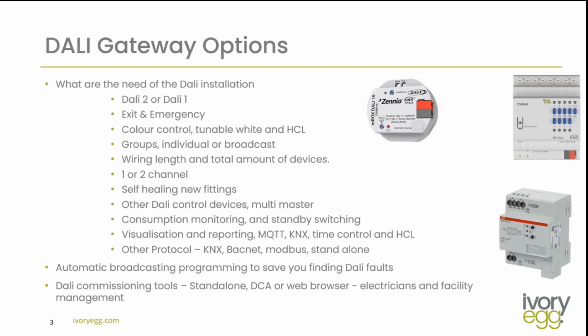And some of the requirements or needs for the DALI installation, is it a DALI 2 drivers or are they DALI 1? Are you doing any exit and emergency testing? There's gateways that have all of the above and board plus the exit emergency testing. Is there any color control, RGB, RGBW? Is there any tunable white? And is there any human-centric lighting requirements?